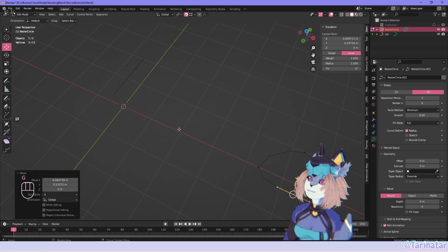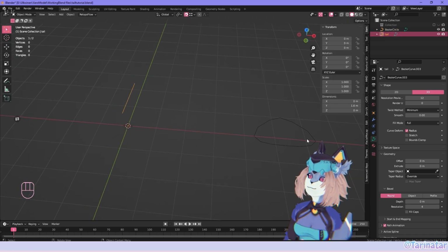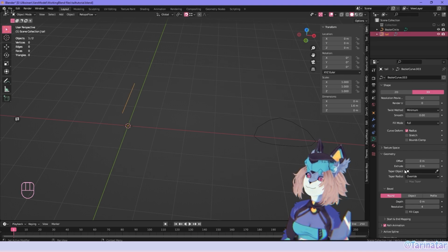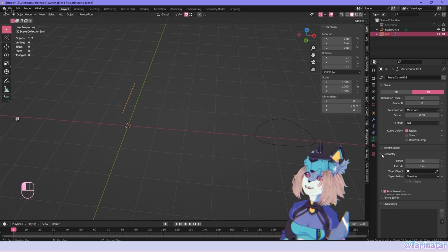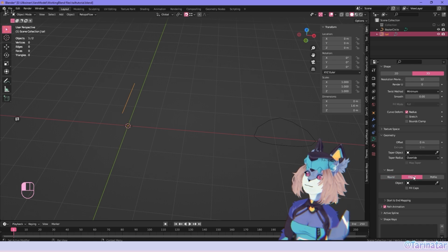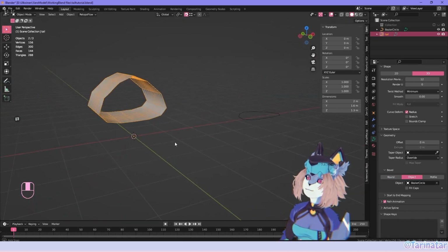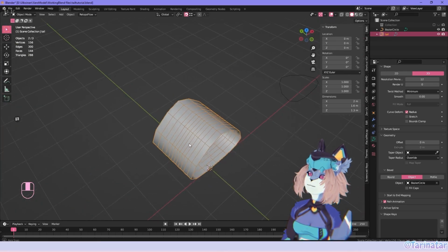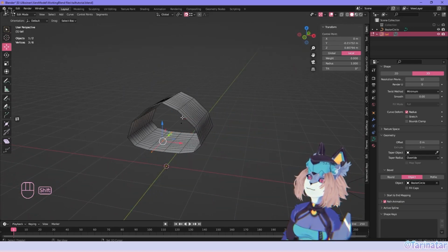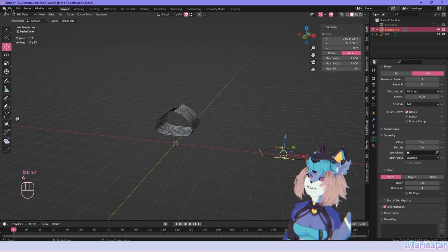That is pretty good. And then we go to the tail and we give it this shape. We do that when we have this one selected. It might be hidden, but it's in the object data properties, geometry, bevel, object, and we select the object we want to bevel it with. And now it is beveled. Then in edit mode, we can change the size. It's quite large now. We can change the size by changing this size.